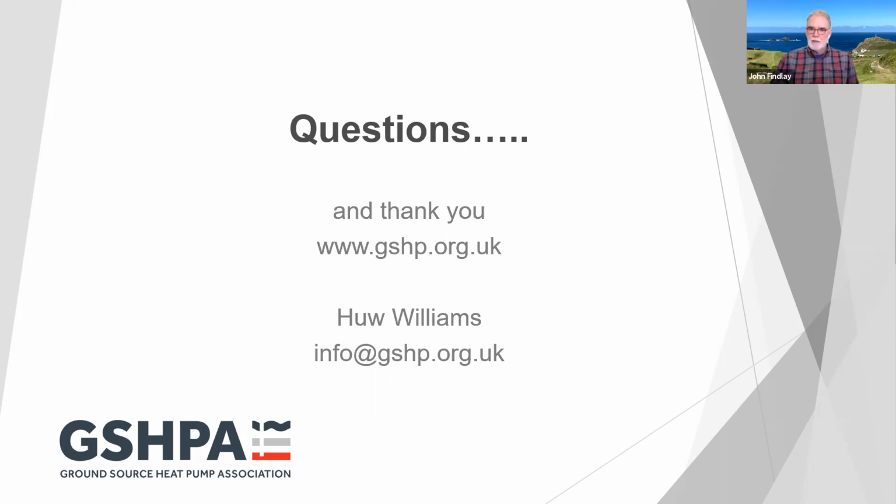Okay, and a question from Peter McConvey. For a new scheme for areas where other open loop schemes are operating, do you model the heat and cool effects from each system on the aquifer to see the interference effects? Yep, that's a really good question. And certainly that's something that's becoming increasingly important, particularly with the multiple projects that are going on in urban areas nowadays. We do. I didn't touch on much of the modeling process, other than to say quickly that we create initial conditions, we calibrate that model, and then we do predictive runs.